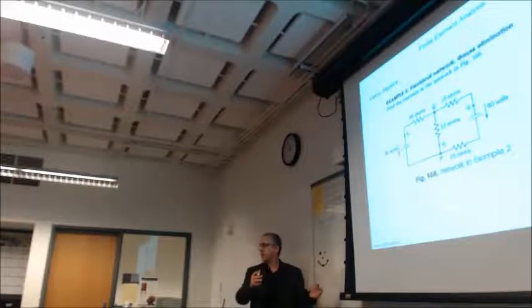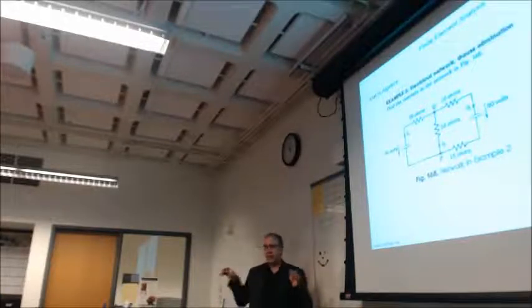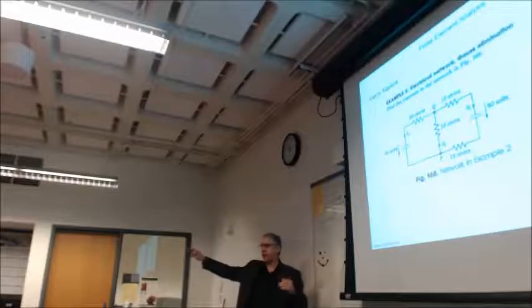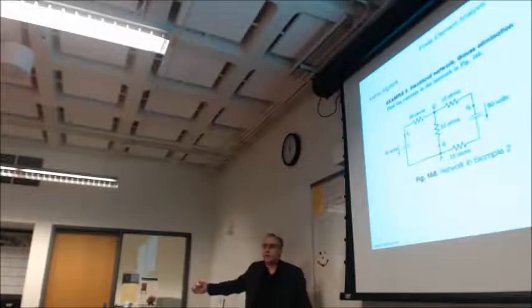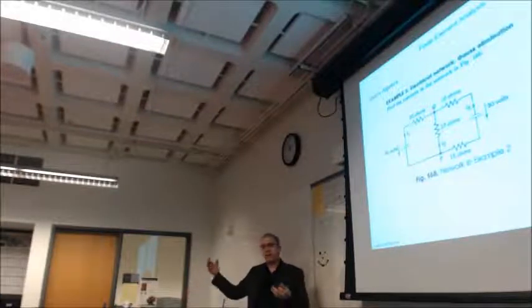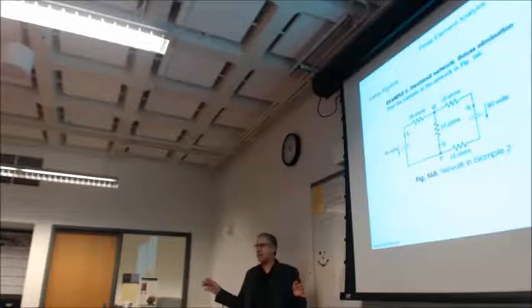And that's where this becomes so cool. Especially, of course, any advanced material, like composites, right? I mean, you literally want all the fibers in one direction on the top and bottom of a spar of a wing, because who cares if it's anywhere else, right? For the normal operation of the plane, that's all that matters. That means you can make a very light structure, purpose-built, nice.